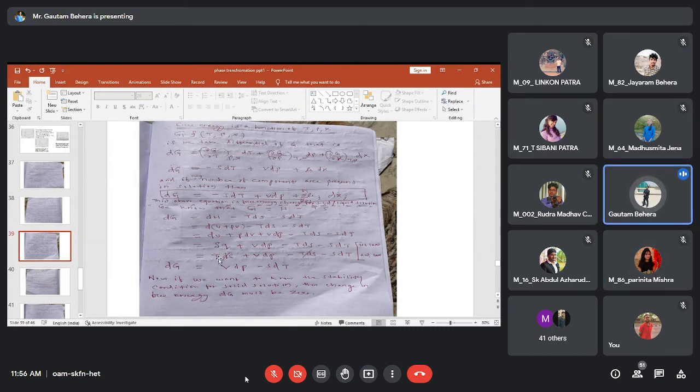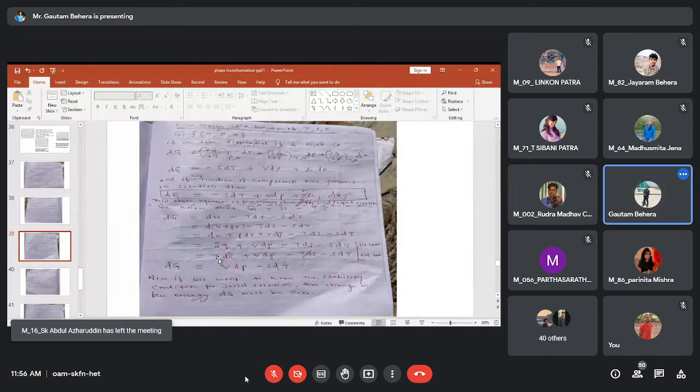Because we know that ds is equal to del q by t. Is it correct? Yes, sir. So similarly, we know that ds is equal to del q by t. So obviously, if ds is equal to del q by t, then del q is equal to tds, right? So instead of del q, you can write tds, right? Then the other expressions remain the same, vdp minus tds minus sdt.